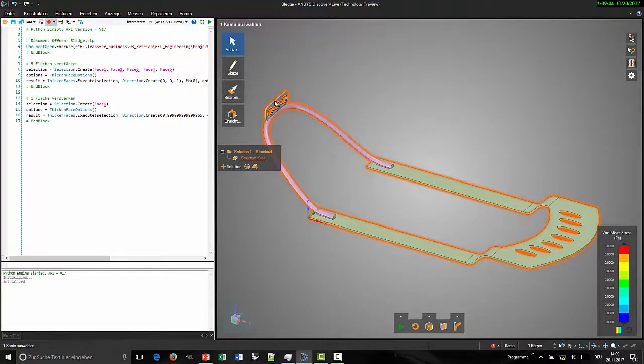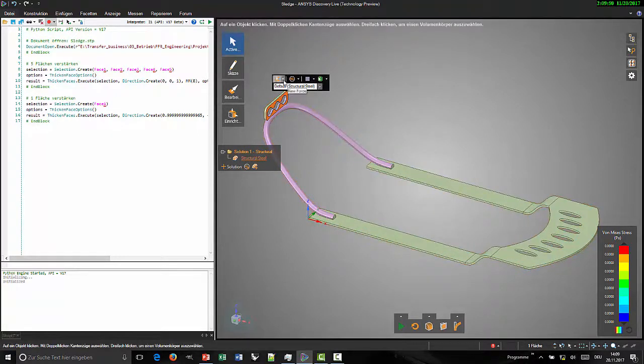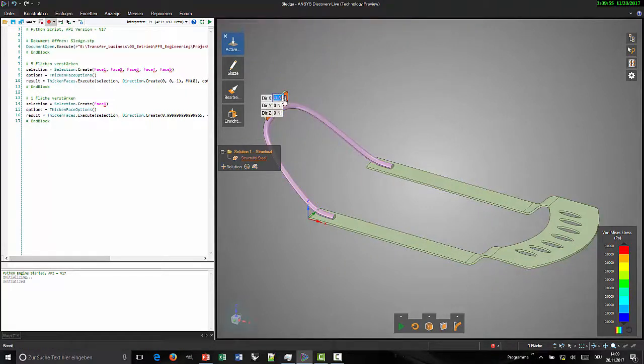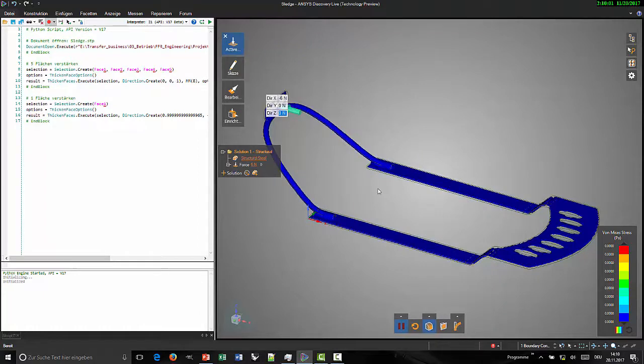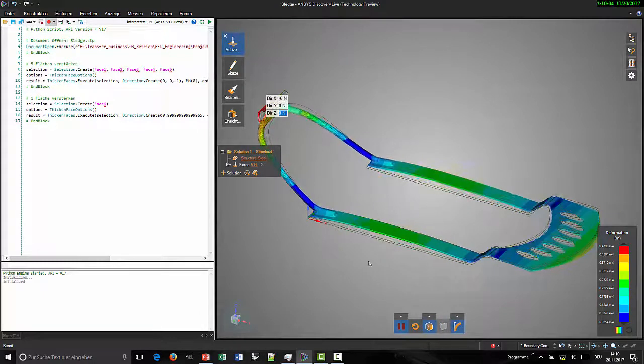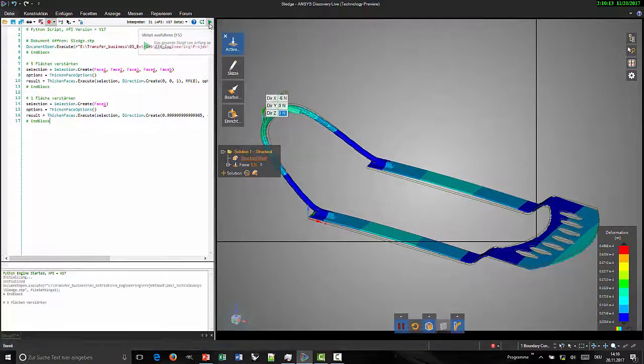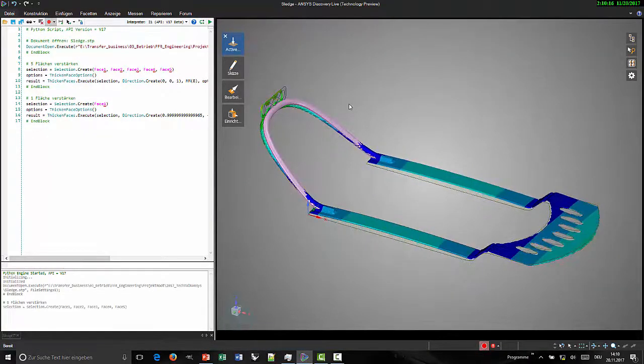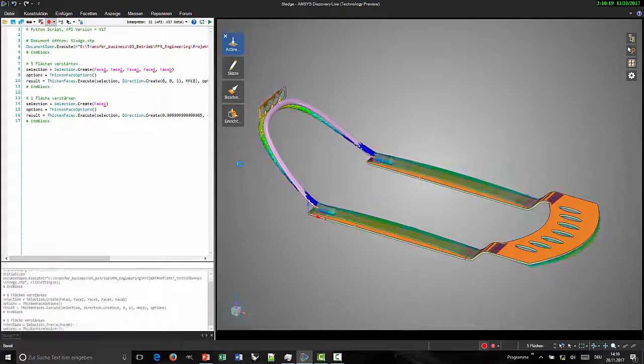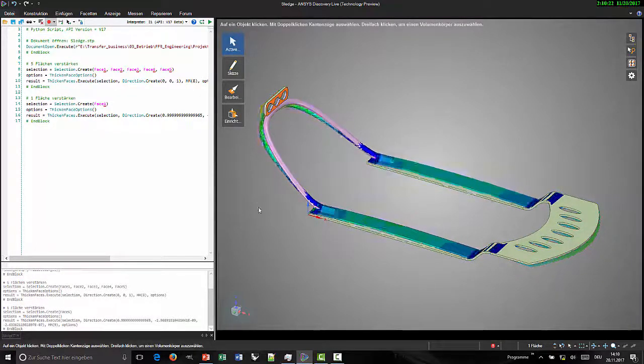But typically first you have to limit design space, especially in huge multi-objective optimization problems which you typically have in engineering, and give the engineer an intuitive approach to limit the design space by his ideas, knowing what target values he might tackle. I think that's typically a very nice feature, so you can here play around. You can run that script now after you have recorded it. So what will happen is that the whole model will be reloaded, and you can also play around a bit with, for example, the thickness of the extrusion of the upper part.